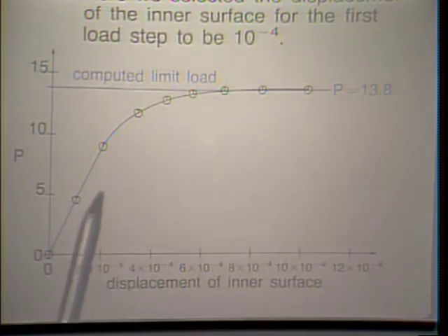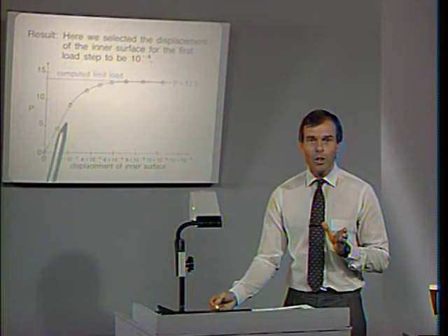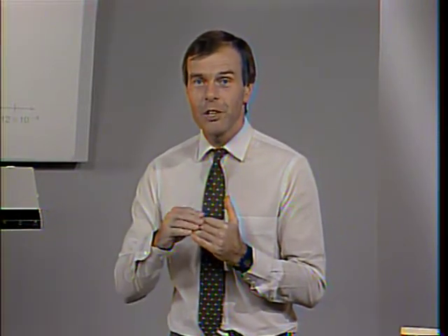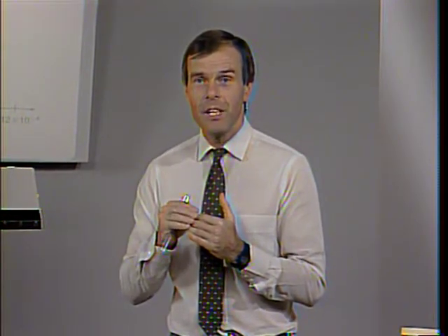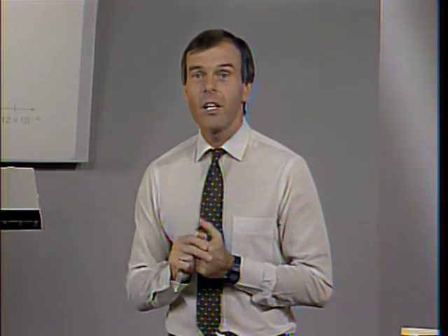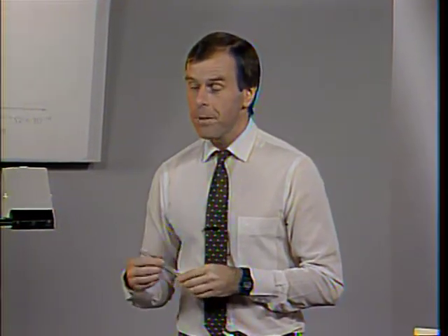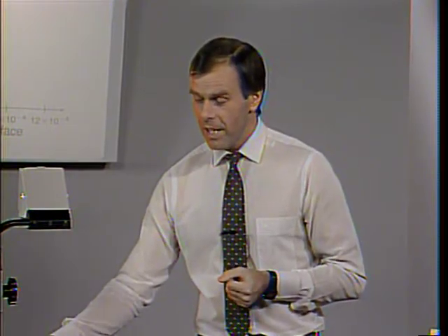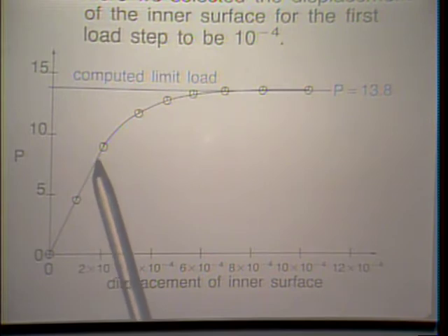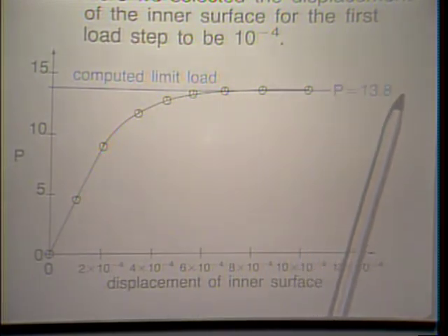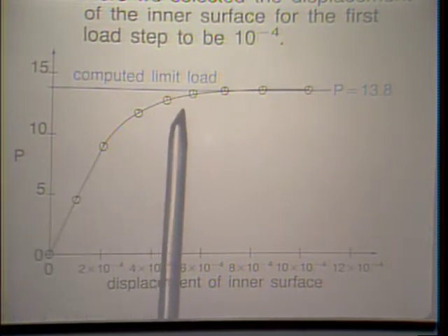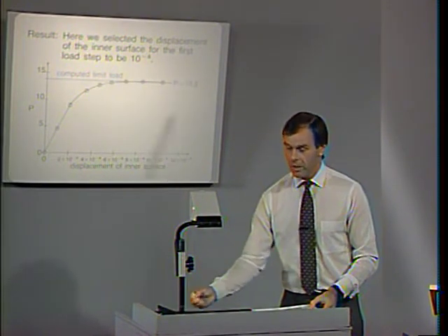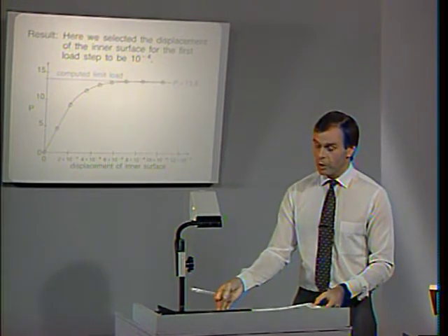And this is the difficulty that I referred to at the start of the last lecture. You see, if you use the earlier solution algorithms, you have to very slowly, with restarting or a very judicious choice of a load function, get yourself closer and closer to the limit load. And that can be time consuming, and that means it also consumes quite a bit of computer cost as well as cost of your time, and therefore it is so much more convenient to use an automatic solution algorithm in which you don't need to specify a load function, that simply marches up here and gives you the actual collapse load quite easily as shown here. Notice an interesting point is that we actually march along this plateau when we use this automatic solution algorithm.